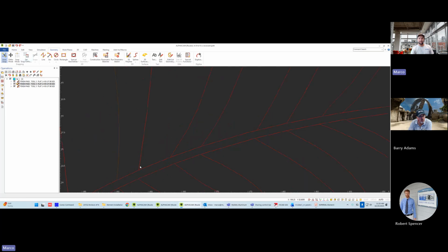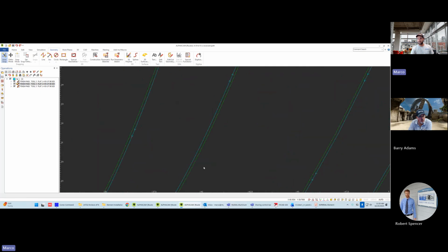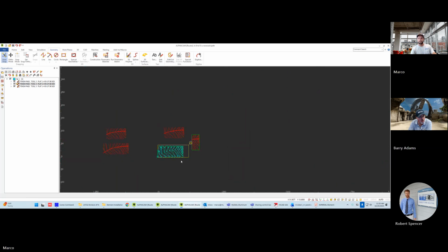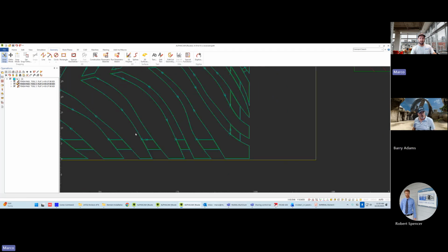I think I just had to break the elements so I didn't have any of the bottom returns, but then this is the finished product that we actually cut. So you can see, the lines came out all nice. Yeah. Well, that's how you do that. I left these little chunks in here as webbing to hold the sheet together while they put it in the frame. And once it's welded into the frame, they're going to cut all that out.